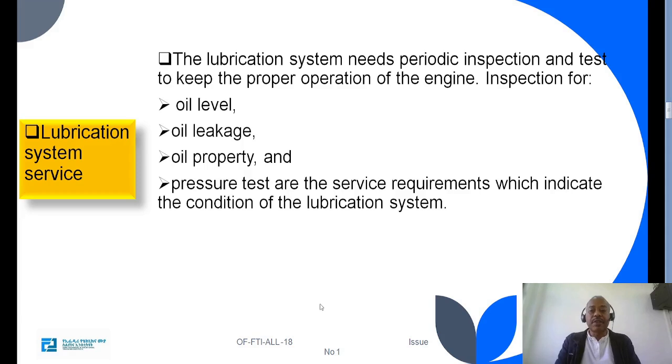Lubrication system service. The lubrication system needs periodic inspection and tests to keep the proper operation of the engine. An inspection for oil level, oil leakage, oil property, and pressure tests are the service requirements which indicate the condition of the lubrication system.